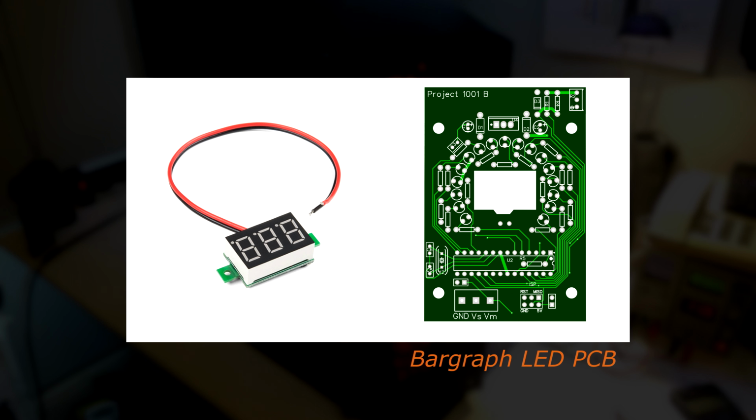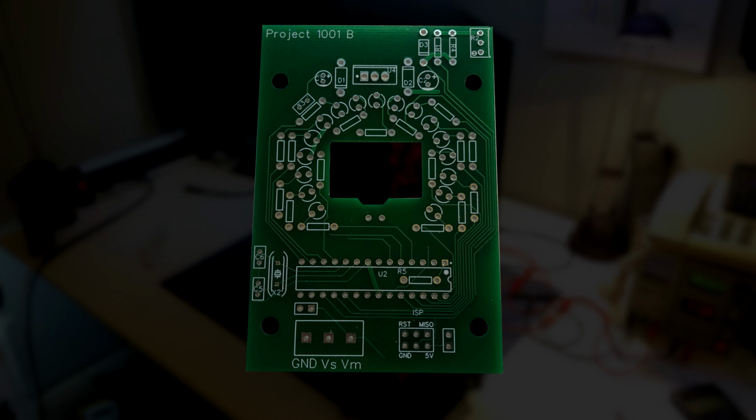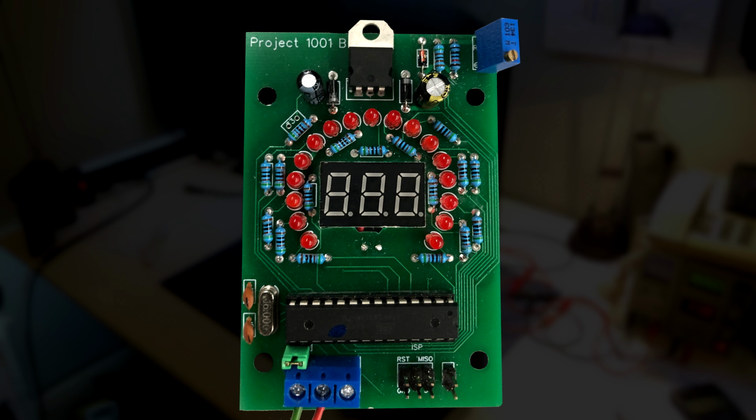And there is the circular LED bar graph, which is a board I designed. Arduino based, with 17 LEDs driven off it. One ADC is used to sense the voltage input and translate it into the bar graph. More voltage means more LEDs turn on.